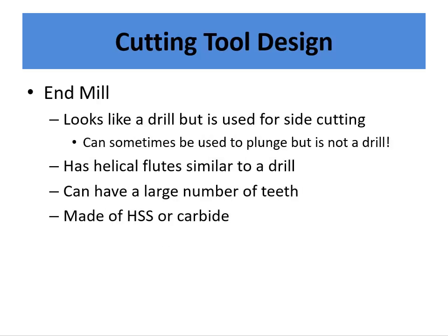So an end mill. It kind of looks like a drill, but you use it for side cutting. And unlike a drill, most end mills, even if they're center cutting, you don't really want to plunge straight down with them. If you already have a hole made and you want to open the hole up, now you can plunge down through because you're not actually cutting on the center. But on an end mill, you don't want to cut with the center of an end mill. It's not designed for that.